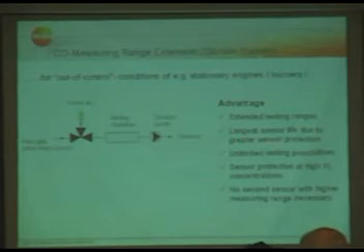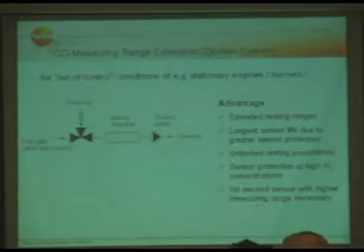And this is also useful if you have to do long-term tests, because some regulations say you have to measure for 1 hour, no matter how high the concentration is. If you calibrate the sensor and the dilution system, you will be within 5% accuracy, and then you can expand the measuring duration up to 1 or 2 hours without destroying the sensor.